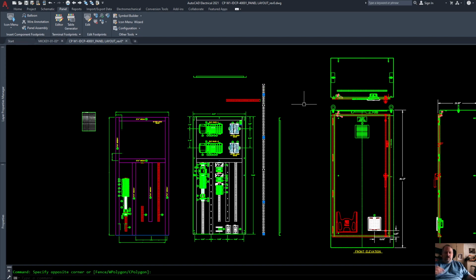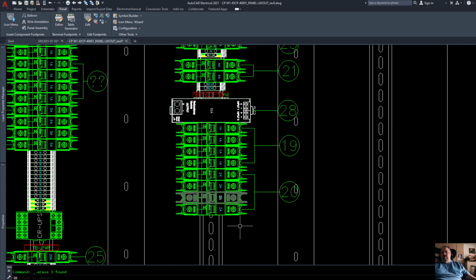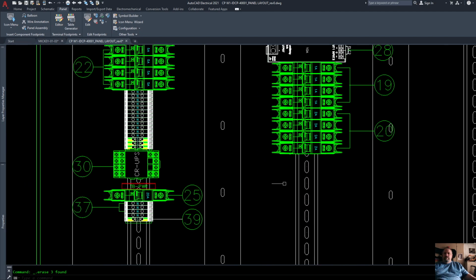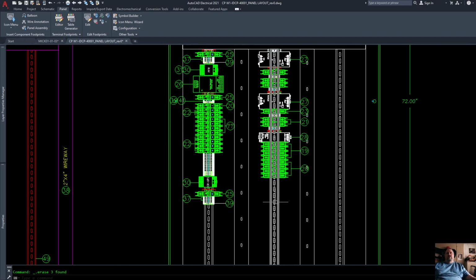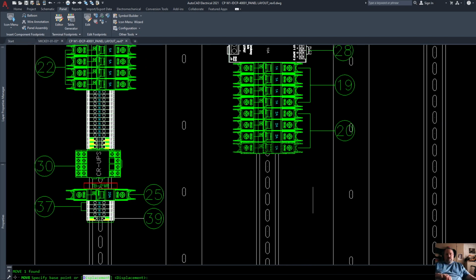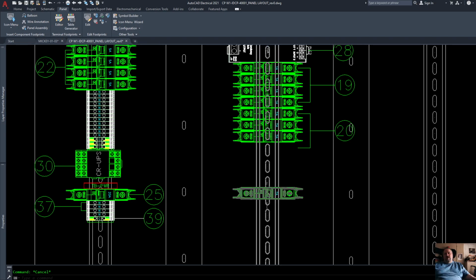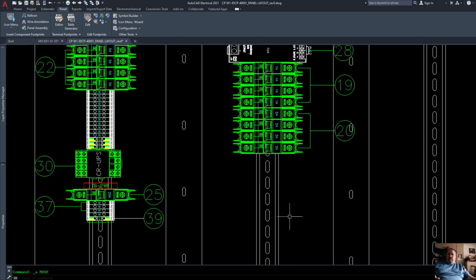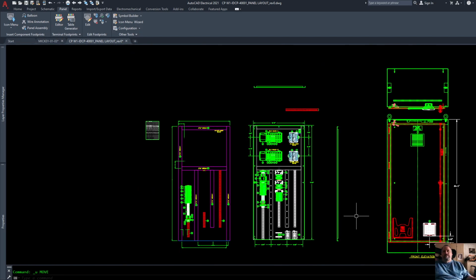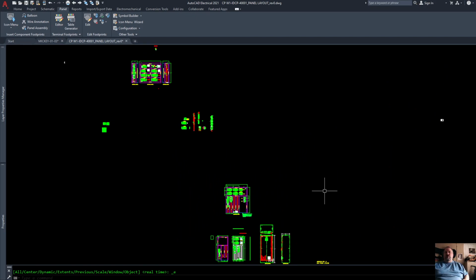You will insert it in, and then once you make your components, you will put your wipeouts on your components. So once you insert them on the Dinrail, it's still there. See, if I highlight it, everything shows up. But since I have the wipeouts on each individual part, they cover up the Dinrail. That way, if you ever move a piece, move it there, the Dinrail shows back up, and it hides it in the new spot. So that saves time. That is how you actually insert them.